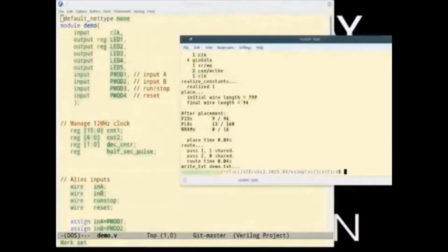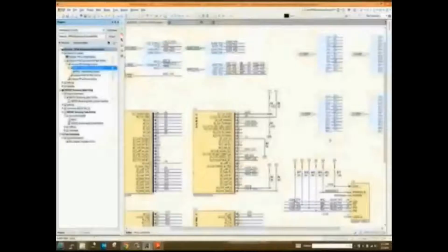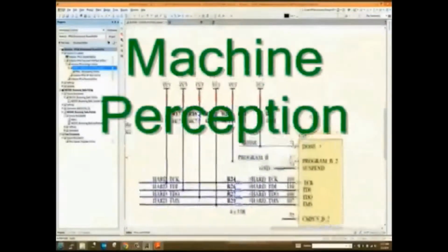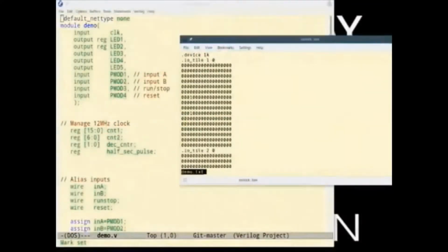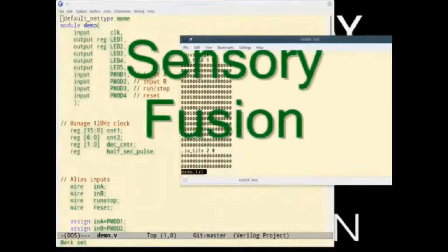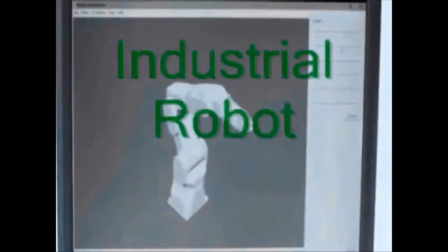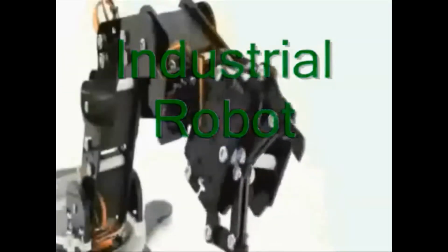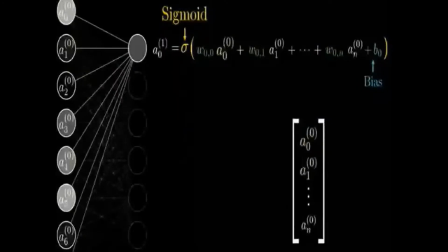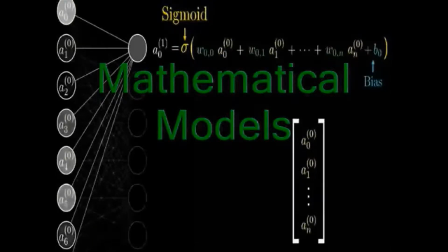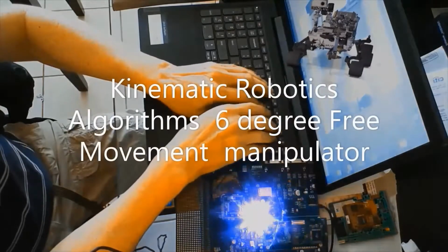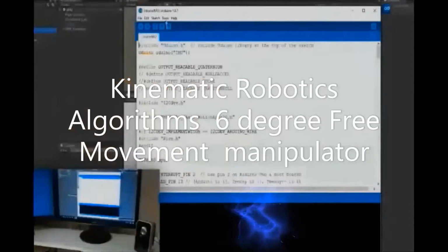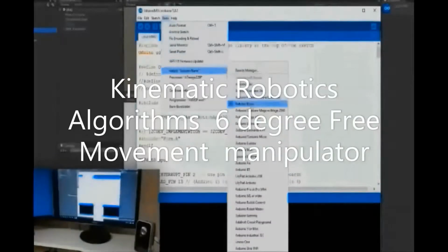The kinematic robotic arm is characterized by the use of algorithms of reading points of 3D space, floating interpolation by a polynomial of the 5th order, iterative process of solving inverse kinematics tasks, dynamic feed-forward torque of each motor, and calculation of position control algorithm with a control loop.